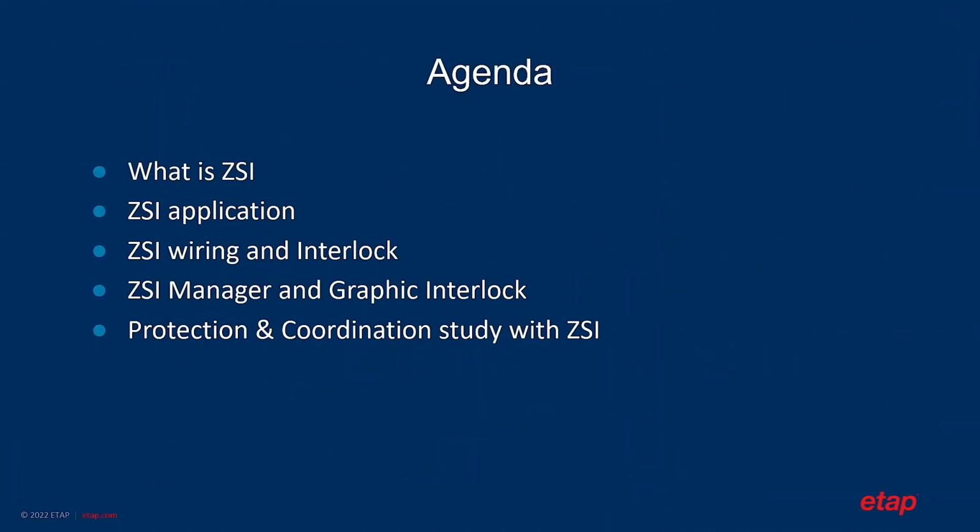In this presentation, I'll explore the use of ZSI, starting by introducing what ZSI is and what the applications of ZSI are, the ZSI wiring and interlocking, the ZSI manager and graphical interlock, as well as how you can use ZSI for protection and coordination studies.